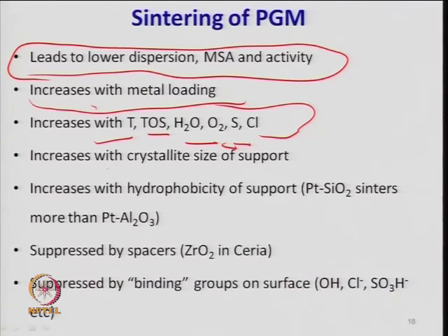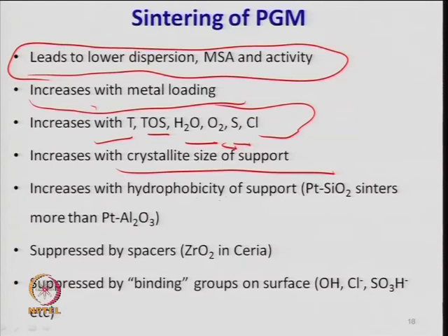Sintering increases with the crystallite size of the support. If the crystal size is high, then your sintering is also higher, so sintering depends on the crystal size. When you have sintering, the crystal size will increase. It also increases with the hydrophobicity of the support. So whether the support is hydrophobic or hydrophilic, again your metal surface area and activity become a crucial factor depending upon the surface.